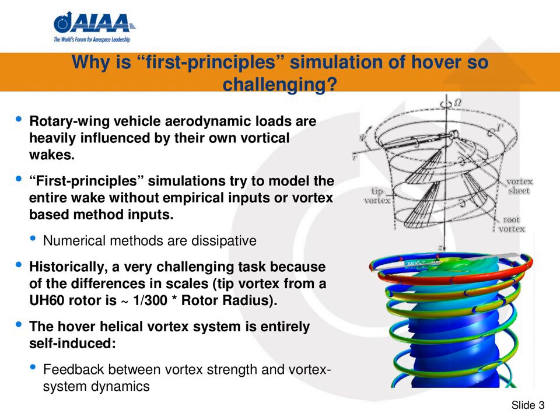Classically, rotorcraft vortex systems are referred to as the wake. The first principle simulations try to model this whole thing without any external inputs, either empirical or reduced order models. The trouble, obviously, is that the numerical methods are very dissipative, and the biggest challenging task here is that if you imagine a rotor blade and typical CFD measures to the far field would require at least a 9-10 span-wise extent